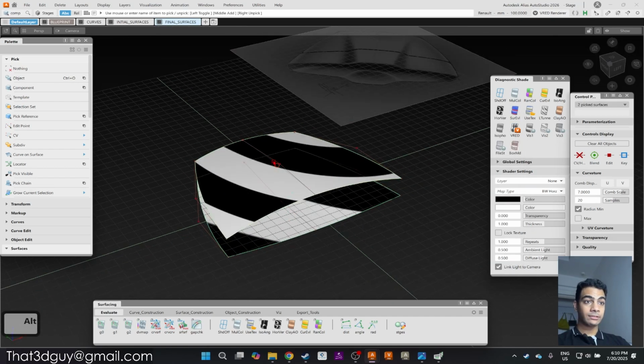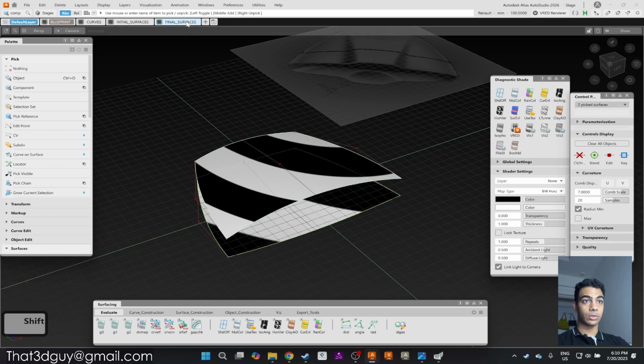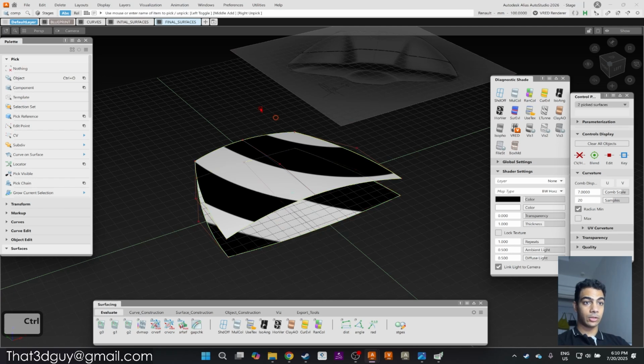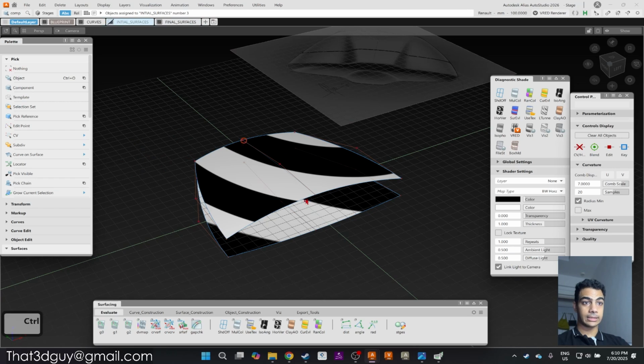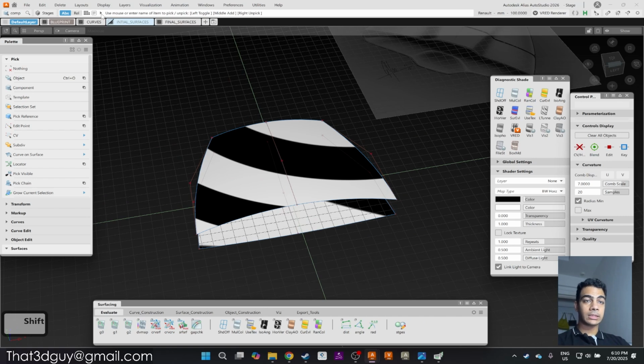So when I have something like this over here, I'll just duplicate this. Just Control C and Control V, and I'll place these ones in the final surfaces. Obviously we lose the history here, so I have something like this: assign objects, and maybe skin in the initial surfaces and just hide. So now we have something like this. Initial surfaces are surfaces that we can use later on again in case we lose some of the data here, or we want to go back to the initial surfaces for maybe changing the history a little, and this will help us to basically model it in symmetry.